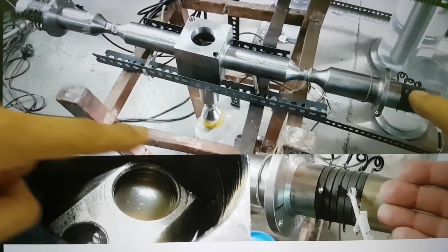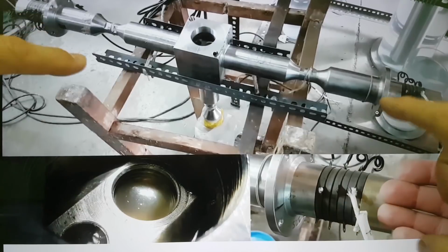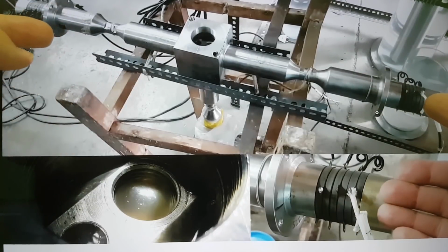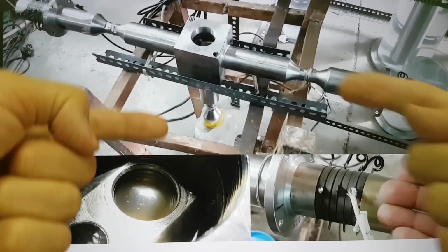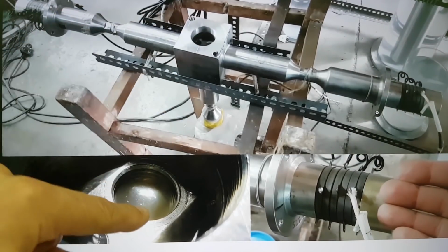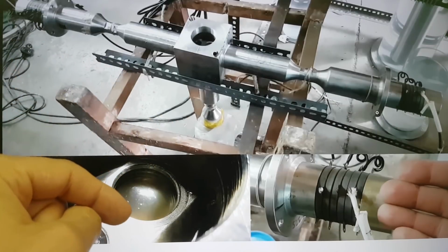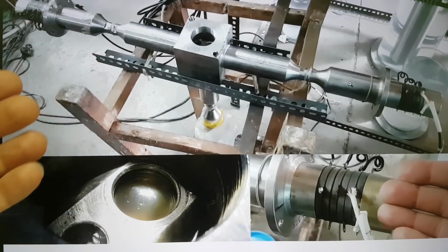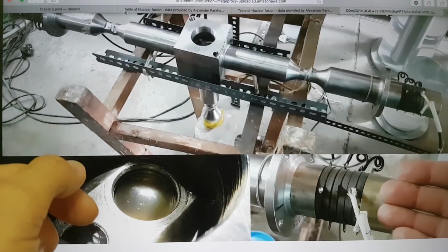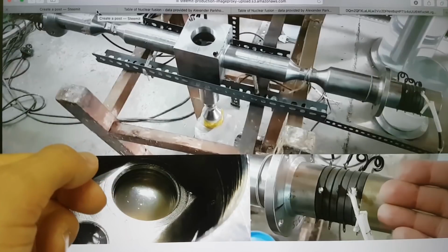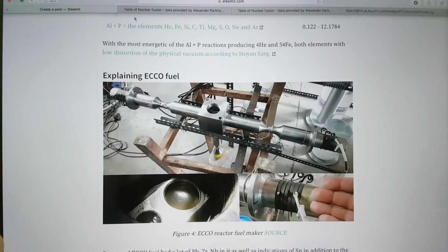And these here and here and here are 3 19.46 kilohertz resonant 1.5 kilowatt ultrasonic horns, and they are cross-axis vibrating into this, and there's a sealed top that goes down on this container. And therefore, they're putting a lot of energy in. And Suhas Ralkar said he didn't see any activity until 120 hours of processing, and he processed for, say, 200 hours.